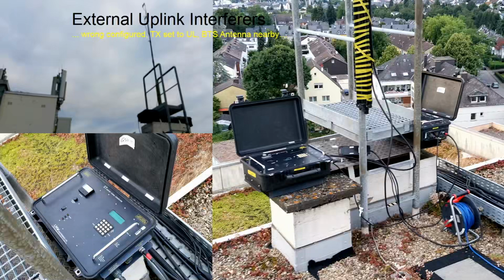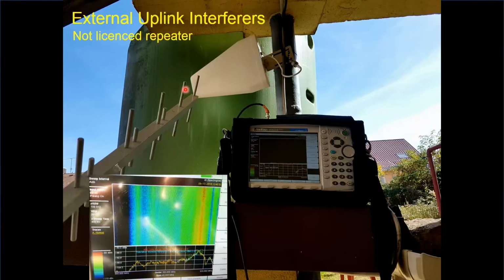Then there are some test transmitters from a subcontractor. They can do test measurements, but if you operate them in the uplink area and transmit there, and there's also the base station antenna, then they overload the receiver, and there are several things that happen.